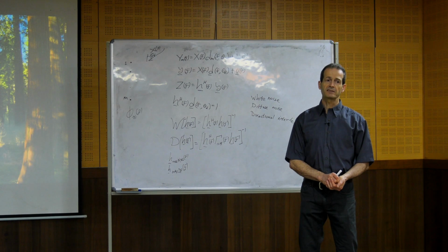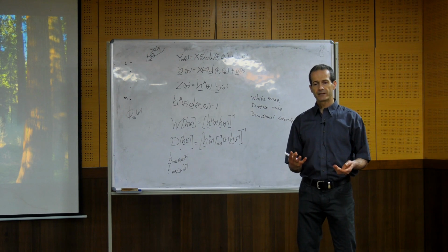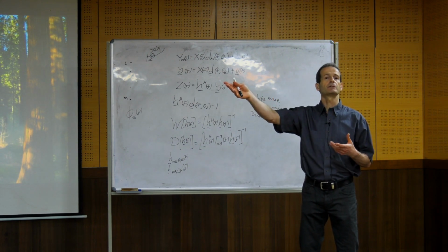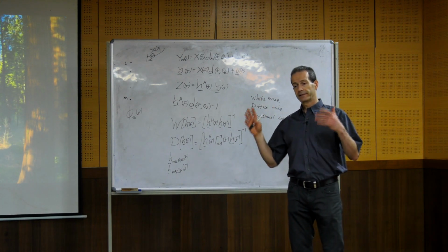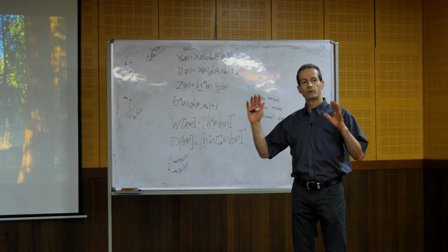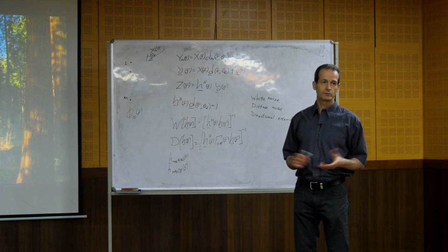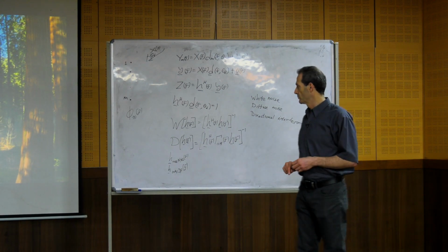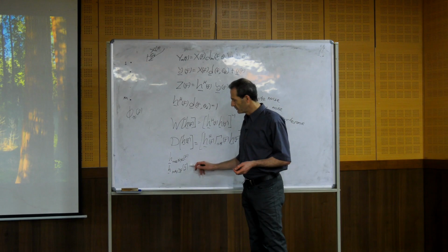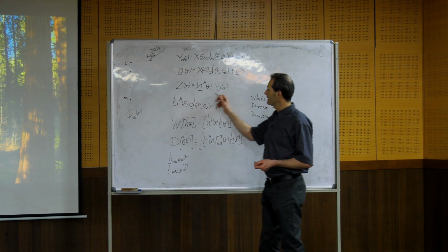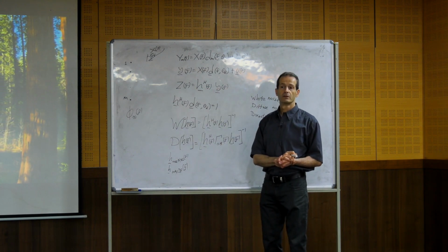Okay? And this is very problematic, because when we design something and we don't know what will happen in the real environment, we need to consider what will happen in the real environment. So if in a practical case there will be also white noise, and actually there is always white noise, thermal noise, and so on, the use of this beamformer will create a very strongly amplified white noise at the output of the beamformer, which is very problematic.